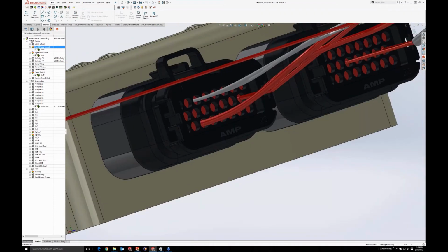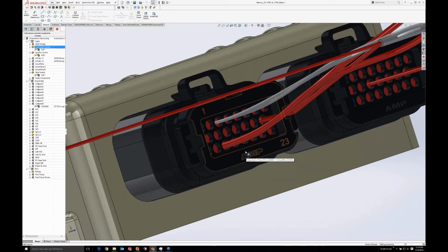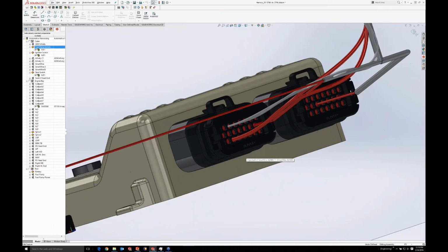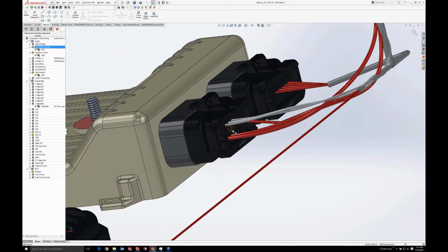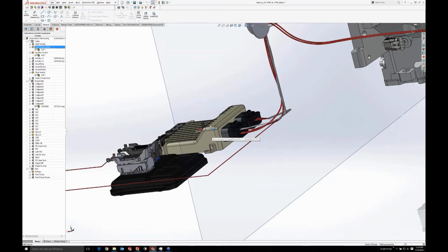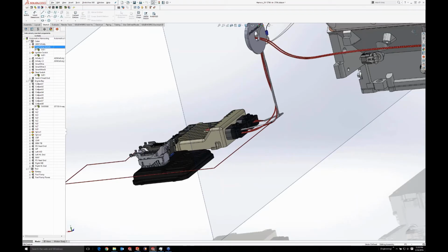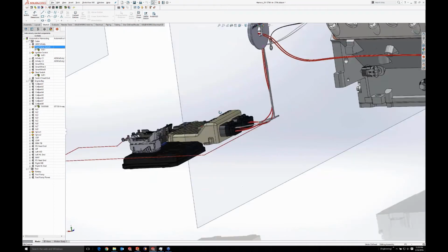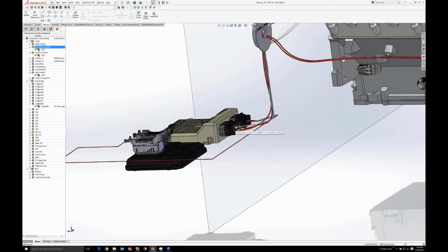And again, I didn't draw these connectors, if you would believe that. I downloaded these. So you mate them in 3D space, workflow-wise. We assign our pin information once. We bring them in through a right-click menu in our electrical manager over here on the left. So we're bringing them in one at a time. We mate them in space, so that's usually, if we're talking to electrical people, where they get hung up: I don't know how to use SOLIDWORKS. But I think any SOLIDWORKS mechanical people would agree mating things in 3D space to an assembly that already exists is not the hardest thing in the world.